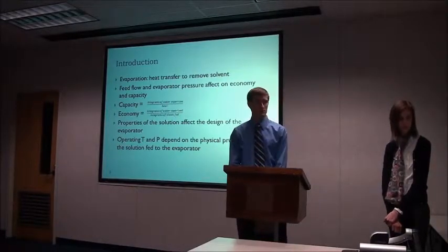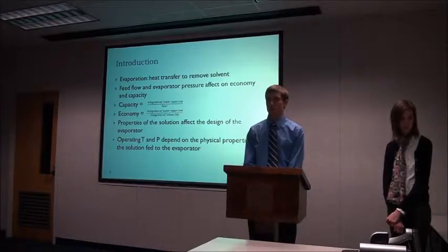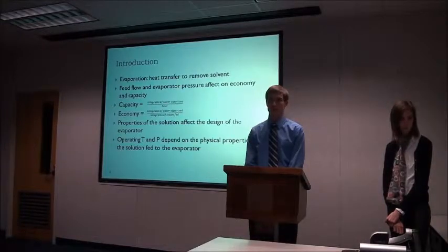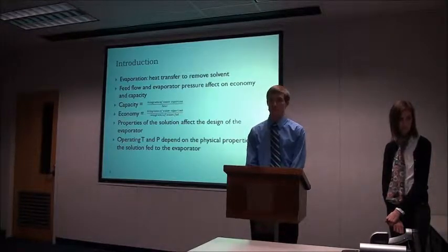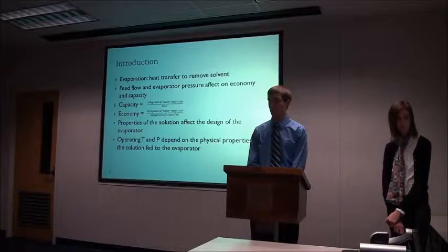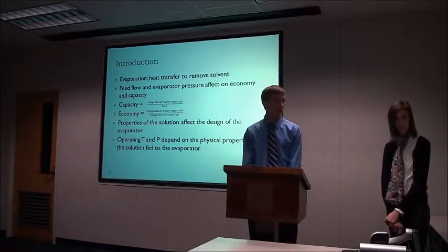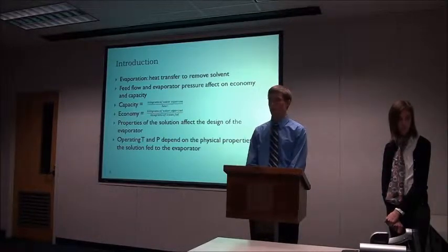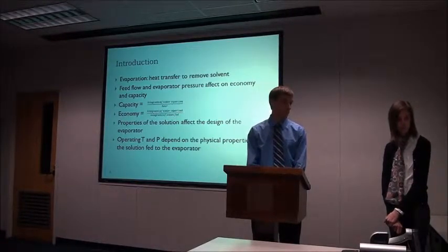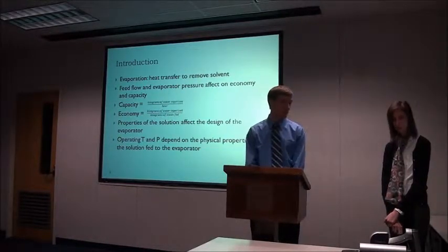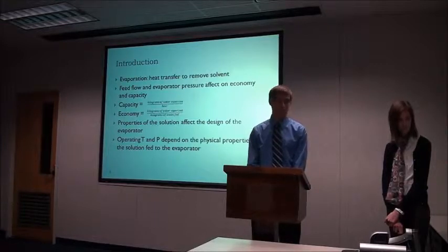The two main factors that influence the design of the evaporator are the economy and the capacity, and those change with feed flow and pressure of the evaporator itself, where capacity is the kilograms of solvent vaporized per hour, and the economy is the kilograms of water vaporized per kilogram of steam feed or whatever you use to heat the solution. And the properties of the solution also affect the design.